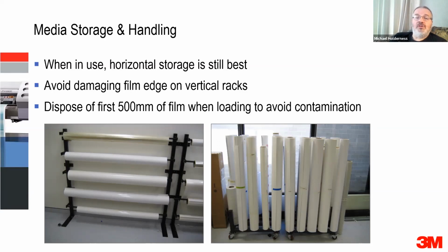So the roll that it had sitting beside the printer had been sitting there for 24 hours, had acclimatized beautifully and printed just wonderfully. So that's why we say try and keep your rolls next to your printer. Even if you're not storing all of them, just keep one roll, the next roll that you're due to open, keep that next to the printer. It will make your life so much easier.